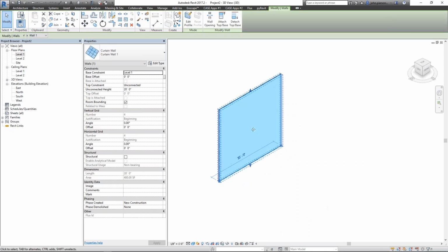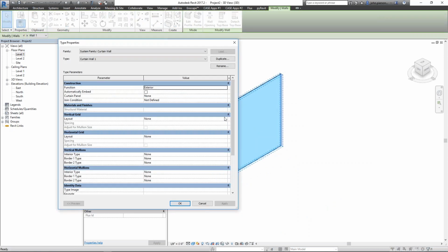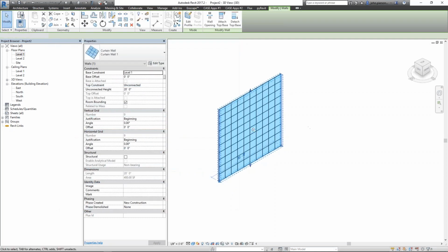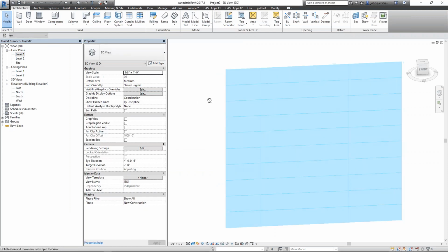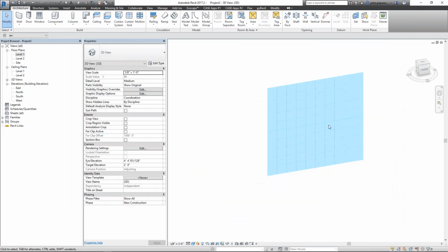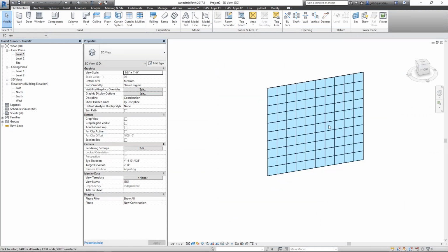What we're able to do in Revit at least is set out a layout rule for curtain walls. So if I edit the type of a curtain wall, do fixed distance at like 2 feet, I'm going to define minimum panel sizes. Whatever the project architect wants to be the smallest possible panel, I could set those up. So I now have my minimum panel defined. This is a planar surface that'll have panels that are divisible by 2 feet. It'll be a very normal surface.